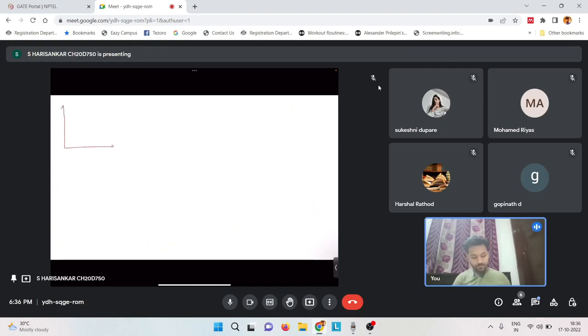So what did we learn in PFR? In PFR, the volume of the reactor is basically the area under this curve, right? This is the volume of the PFR. And now for infinite CSTRs in series, it is equivalent to this, right? So let's say you're taking a CSTR operating line, the volumes are pretty much like this.